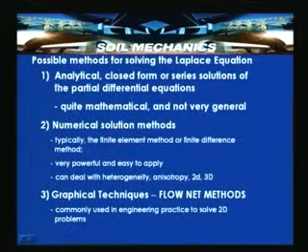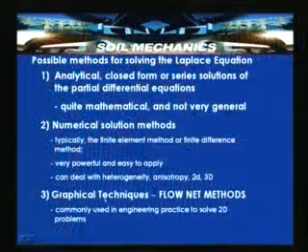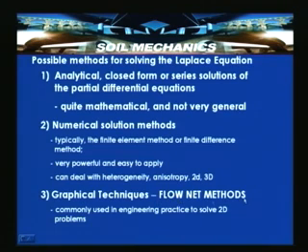The possible methods for solving the Laplace equation are given here in this slide. We are reviewing what we discussed in the previous lecture. First, analytical closed form or series solutions of the partial differential equations, which are quite mathematical and not very general. Another method is the numerical solution methods, typically the finite element method or finite difference method, which are very powerful and easy to apply, and can deal with heterogeneity, anisotropy conditions and 2D and 3D conditions. The third method we are going to discuss today is graphical techniques, that is flow net methods, commonly used in engineering practice to solve 2-dimensional problems.